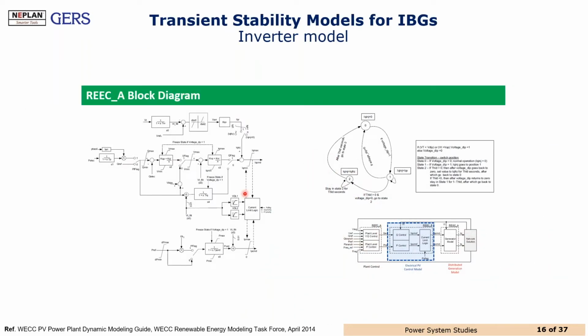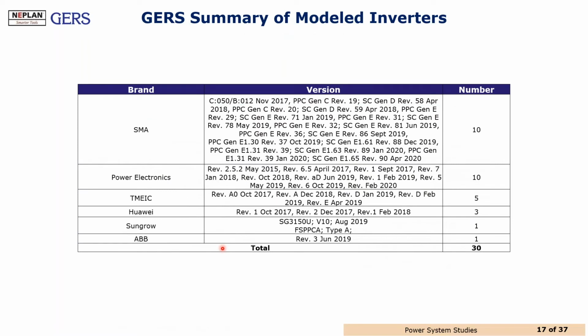Let's talk again about the transient stability, since this is one of the main challenges speaking about the connection request or the new requirements on the grid code compliance for the specification of variable renewable energies. Again, I am presenting here the generic models, but what happens if the generic model is not acceptable? We have to create the model and we have to include the specifications per manufacturer to validate if the control system is able to support or not the different requirements on the grid code compliance.